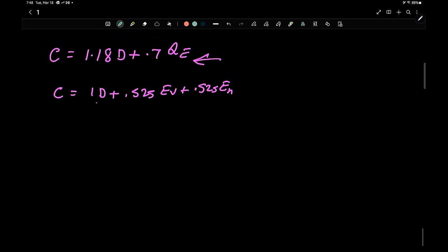So we're going to calculate the roof dead load first. And this is like the video I made about seismic. You got to calculate all the weight of the building. And that was given as 15 pound per square foot. That was given. And then they say the joists are 12 feet long, times 12 feet long.